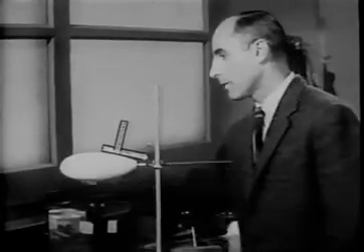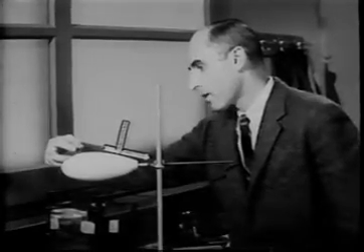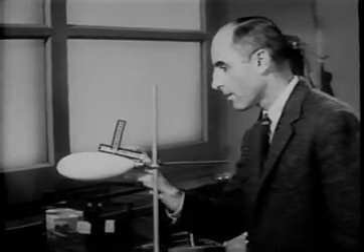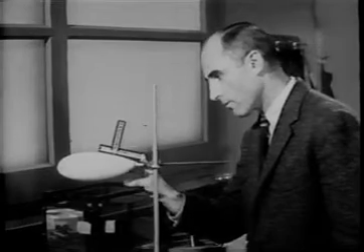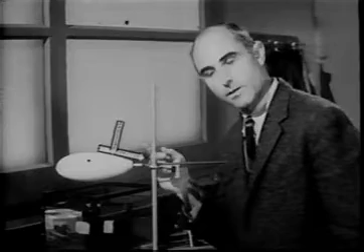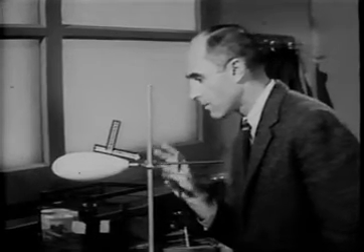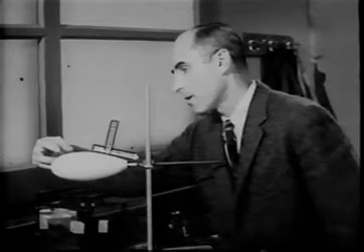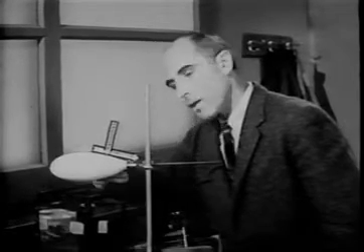Which it is depends on the difference between the average pressure on the front half of the body and the average pressure on the rear half of the body. If the average pressure on the rear half is equal to the average pressure on the front half, then the net pressure drag is zero. But if the average pressure on the rear half is much less than the average pressure on the front half, then there is a large net pressure drag.